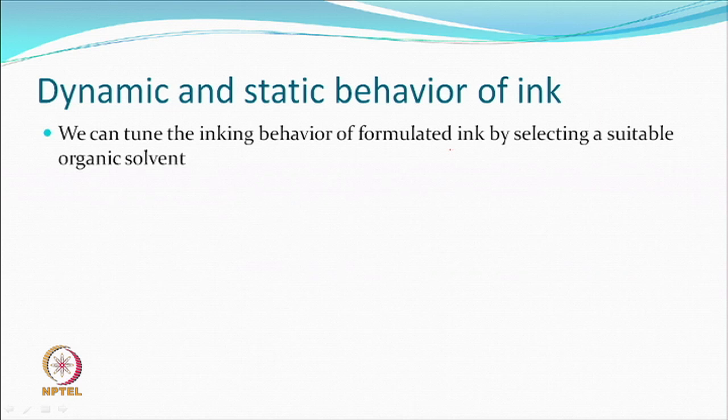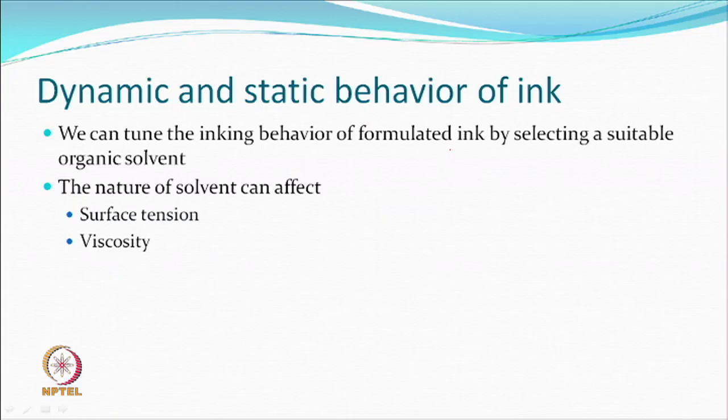But when you are not printing, let us say one of the colors is not being used in that design so much, or the machine had been stationary, there is a drying of the ink at the edges of the nozzle. That can become a particle, a solid material, and so it can cause some issues. So, organic solvents are used. When you add organic solvents or anything, the evaporation rate can be changed. So, the nature of the solvent can affect the surface tension and viscosity.